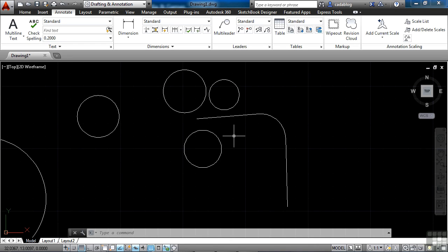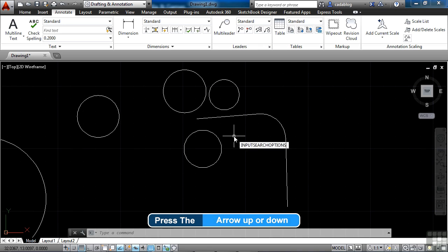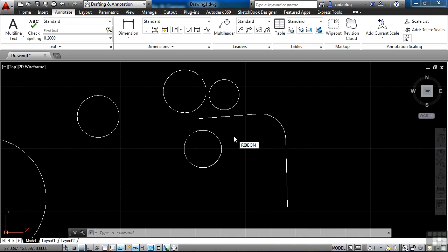Now last tip, if you press the up and down arrow keys, this will toggle you through commands that you've entered. The up command goes up the list, the down command goes down the list. So if you want to find very quickly a couple of commands or just go back from one of the last couple of commands you've done, you can do that very quickly and get to what you want. And again, if it's the wrong one, press the escape key and you're out of there.